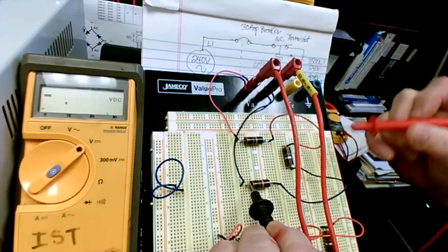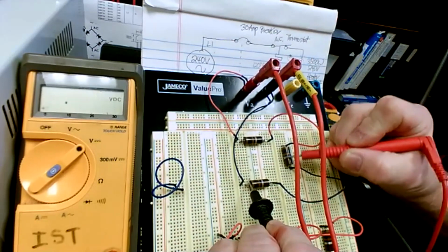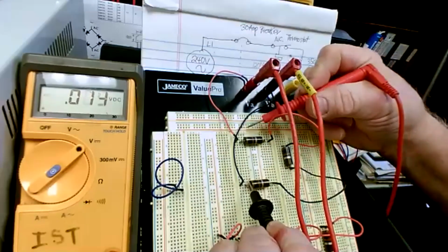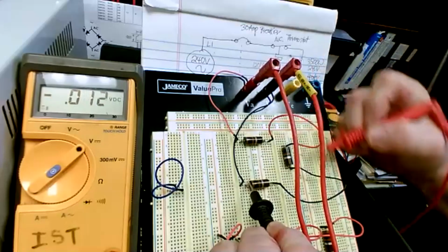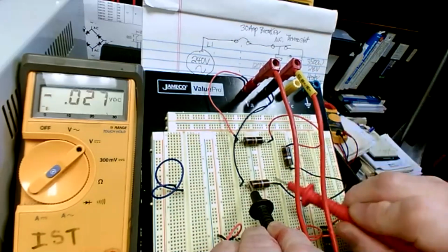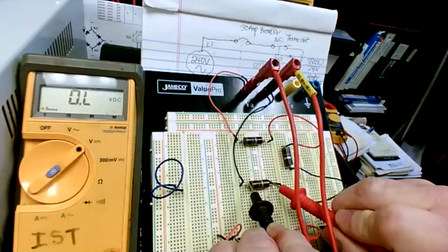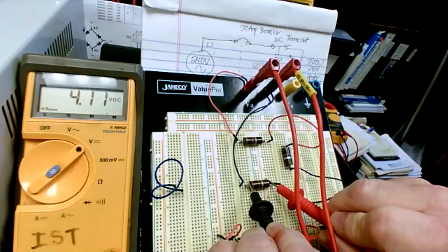Now, if I move to the bottom of the second one, it tells me what's left now. So the second one dropped another 4. It dropped from 12 to 8, 8 entering into here, and now there's only 4 leaving there. There's only 4 volts left for this last one. So the last one gets 4 volts as well. You see it? Everybody got it?